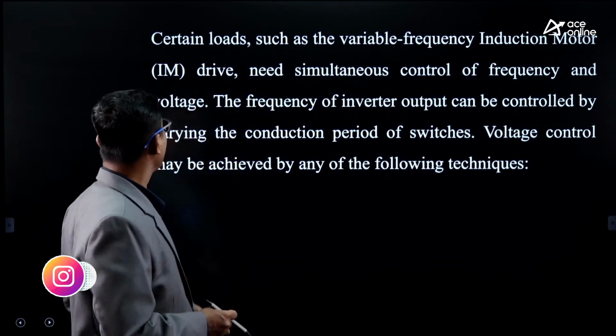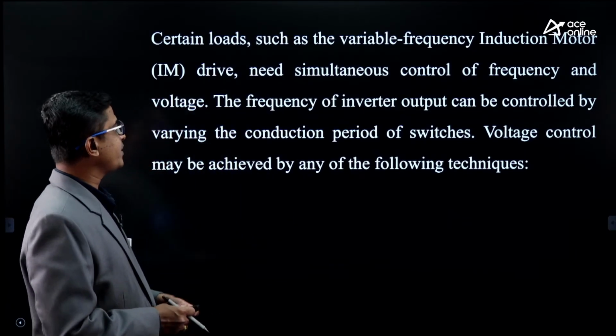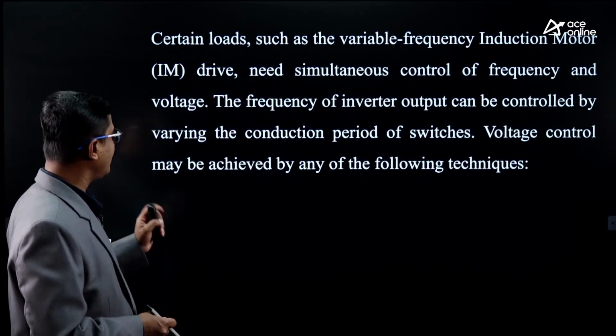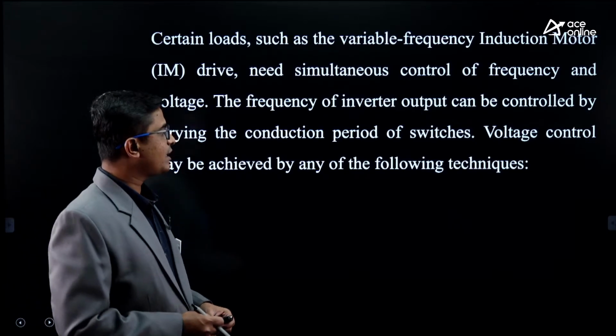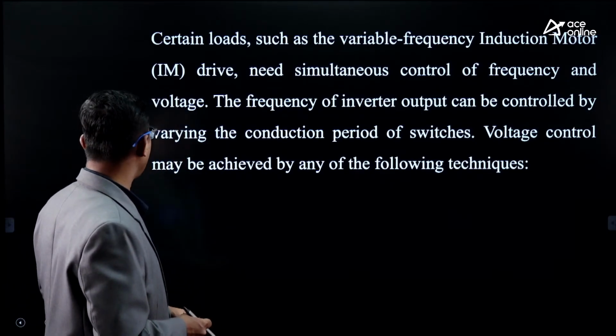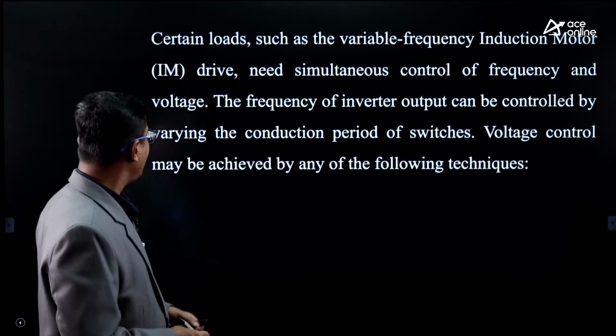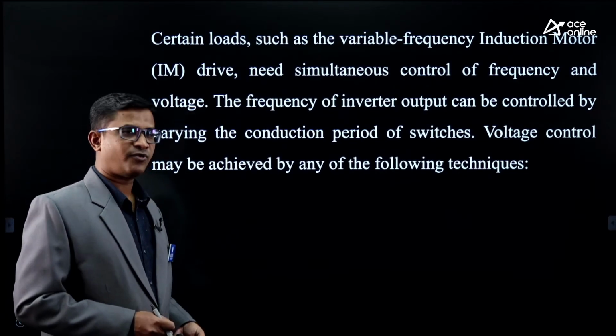So here certain loads such as the variable frequency induction motor drive need simultaneous control of frequency and voltage. The frequency of inverter output can be controlled by varying the conduction period of the switches. Voltage control may be achieved by any of the following techniques.